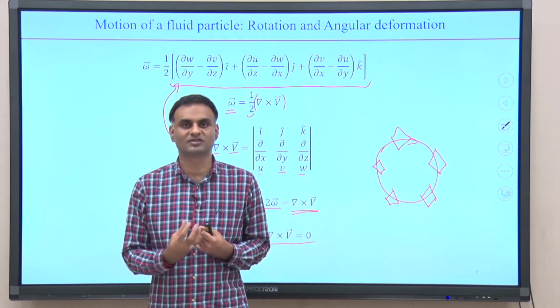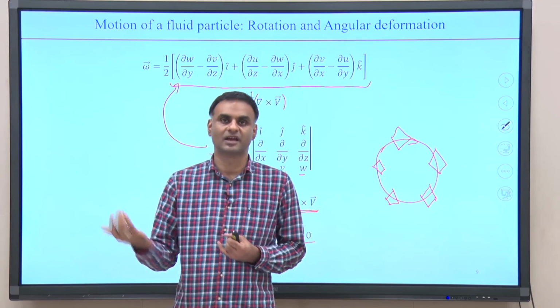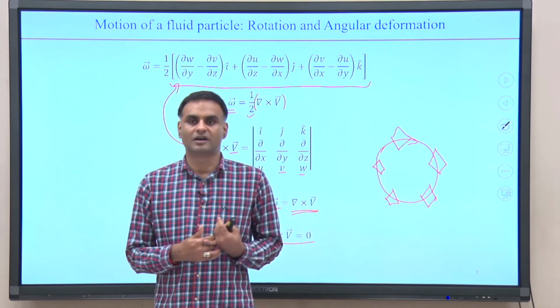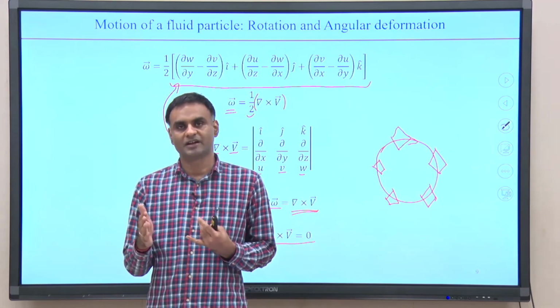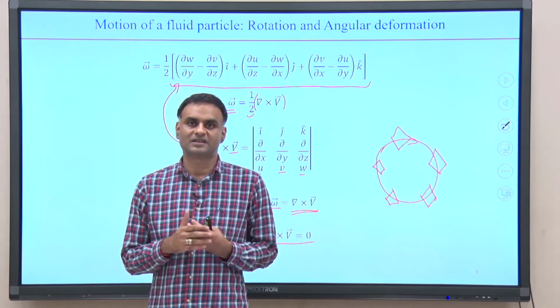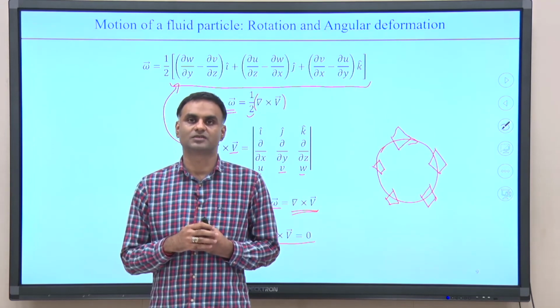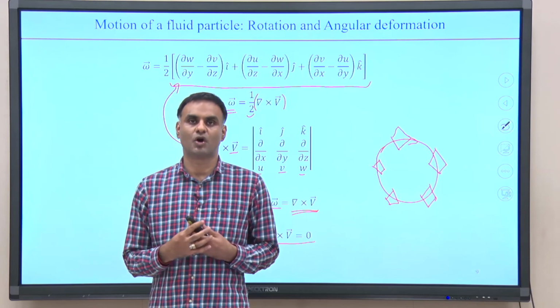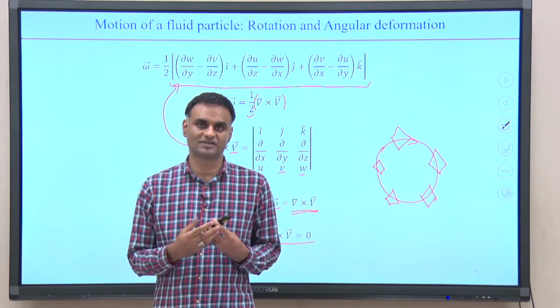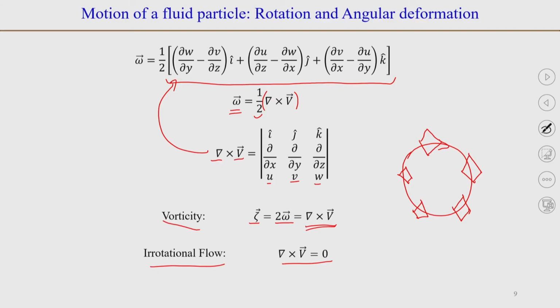So, the rotational force comes only from the shear stress, and as we saw earlier in the definition of a fluid, the shear stress in a fluid is caused by the viscous property of the fluid. So, only for viscous fluids can we have rotational motion. For an inviscid fluid, the flow can be irrotational.